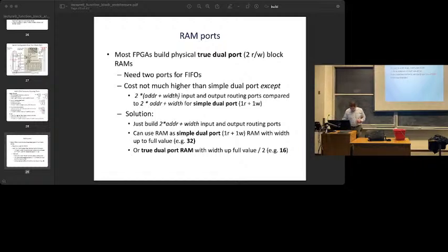So what we need, we can already read it, right? That's what you're actually doing whenever you're using a lookup table. You're reading out a truth table to implement a logic function, but that is actually just a read. But what we need to do is be able to write it. For normal lookup table use, the lookup table is written when you actually program the device. And that's done with special circuitry.